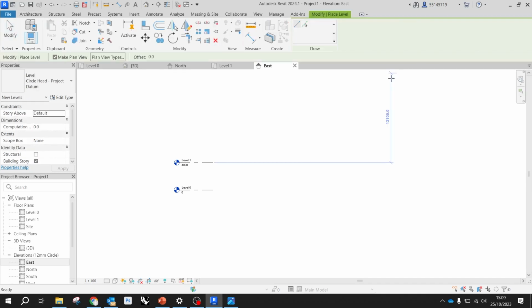So I'm gonna click on it, say new level, and then if I come to my drawing, you see that I'm basically gonna pick where I want my level to be. Make sure up here you have Make Plan View checked. So many times when you will be using commands in Revit, you want to keep an eye on this green bar that shows up, because as it does in Rhino, for instance, on the top bar, it's basically the dialog box when you are using any tool, right?